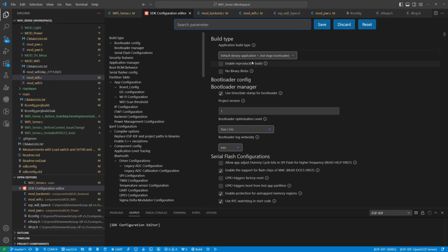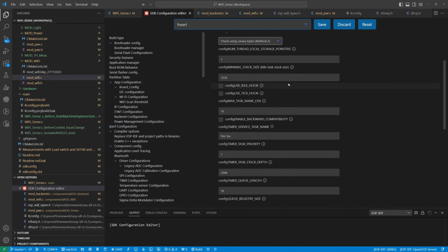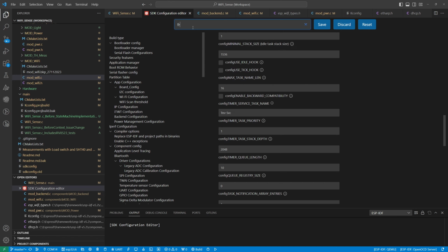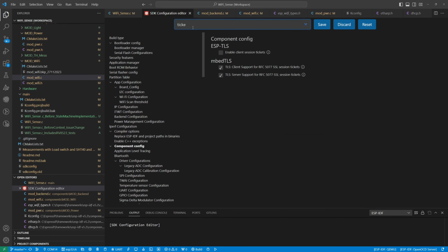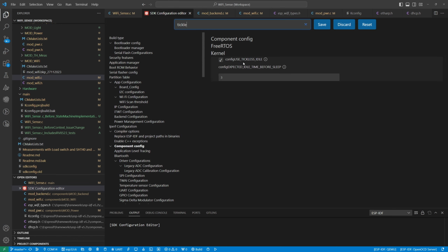Okay, the last one is about FreeRTOS. So if we look at FreeRTOS, there is the tickless, where is it? One sec. Which has to be enabled. This one. That means that FreeRTOS will not generate the periodic tick interrupts. So in order to go into auto light sleep, that means all other tasks that could run should be paused or sleeping, and no other interrupts should occur. Then auto light sleep can be entered.